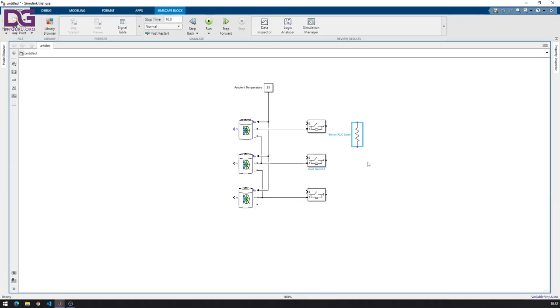We'll rotate this thing, make it a little bit smaller if possible. Yeah, and then we have to connect this in the same fashion as we saw in the PPT. Negative will get connected here, it goes here, and then the gate goes here. We can make it a little bit smaller so we can fit. Okay, yeah, so this is the RLC load, and we have to repeat the same procedure for all 3 again.